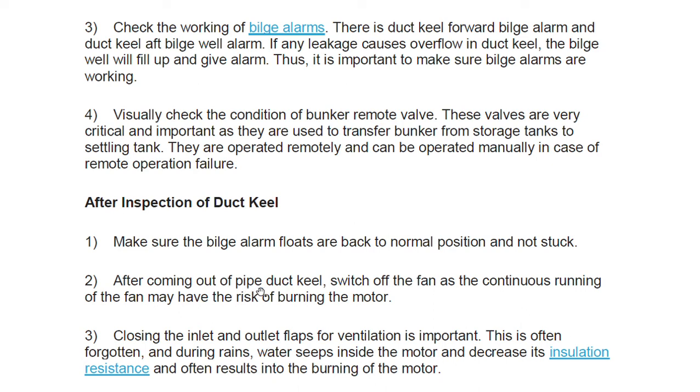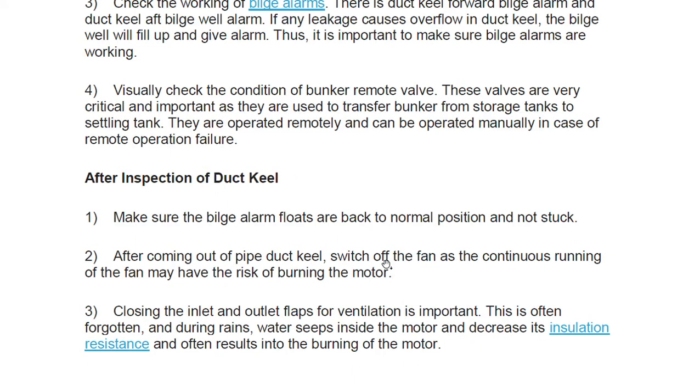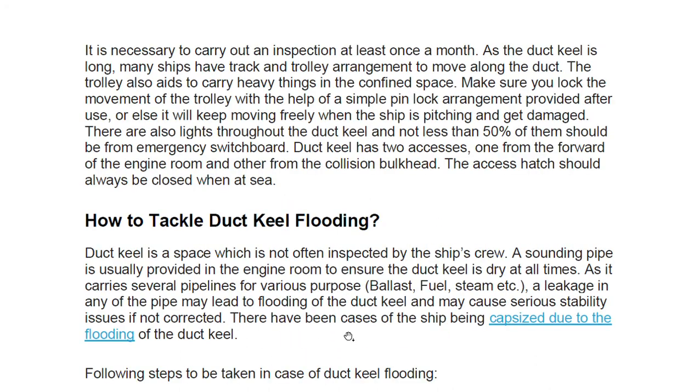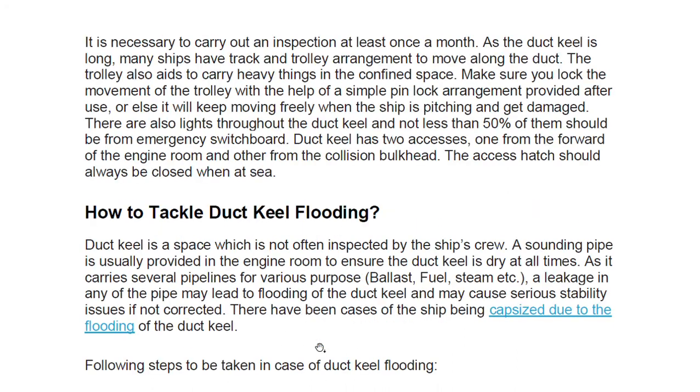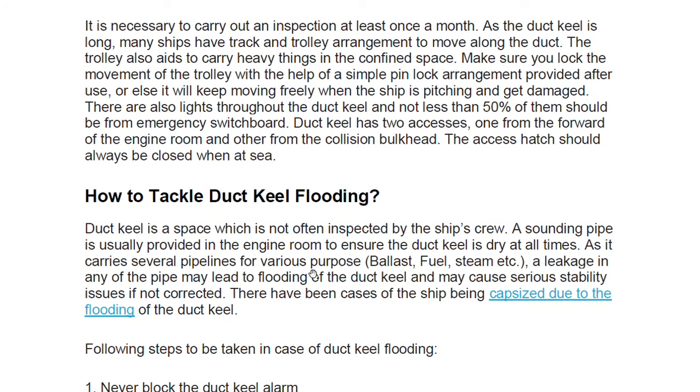After coming out of the duct, we switch off the fan, as a continuously running fan risks burning the motor. Whatever we have done, we set it back. Close the inlet and outlet flaps of the ventilator. Important: this is often forgotten, and during rains water seeps inside the motor, decreases its insulation resistance and often results in burning of the motor. So once a month it must be carried out.